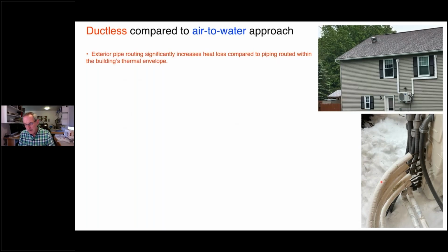There are insulation products that do have UV protection, and you can also buy tapes that you could wrap the insulation with that would absorb the UV. But some of this insulation gets very rigid and it literally starts to just flake away or crack open or otherwise deteriorate based on primarily sunlight. And of course, if you're starting to lose the insulation, you're experiencing increased heat loss.